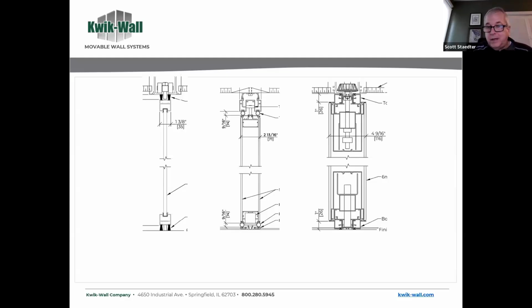And now you go from a panel that basically is 4.5 inches thick, and you got a much bigger airspace between the glass. The glass is still quarter, okay? And you get that big airspace in there, and you get much better acoustics. Whoever works with and specifies demountable walls in office spaces understands that concept, right? The wider you get, the better the acoustics. You can maintain the same level of glass. It's just get that airspace in there. It's the same thing with movable walls, right?